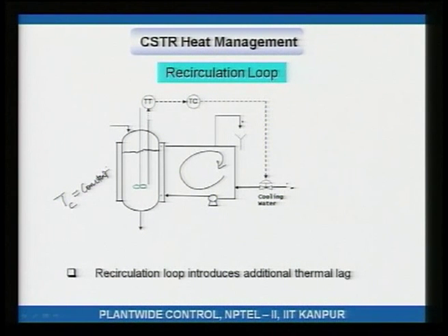Then how do you vary the amount of heating or cooling, or the amount of cooling? So, you see the amount of heat removed, Q cool, is equal to heat transfer coefficient times area for heat transfer times temperature of the reactor minus temperature of the coolant, and I will call it temperature of the jacket, let us call it J. Tj, temperature of the jacket, is constant. Okay. Temperature of the reactor minus temperature of the what? Of the jacket. Yeah.